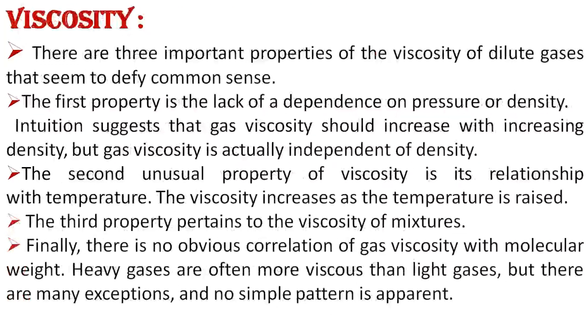So starting with the first parameter, that is the viscosity. There are three important properties of the viscosity of a dilute gas that seem to defy common sense. The first property is the lack of dependence on pressure or density.